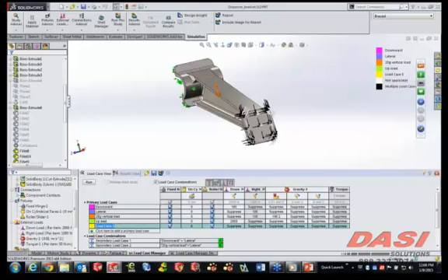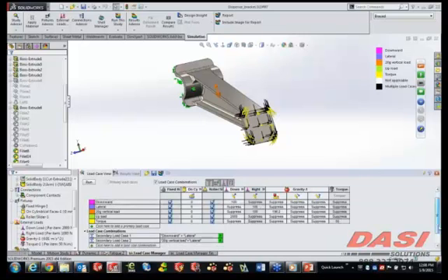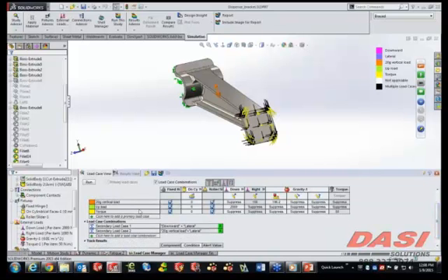We'll call it whatever we want. And now I can turn on whatever restraint or force I want, in this case the torque force. You can also create these load case combinations. Now, what a load case combination amounts to is different scenarios combined with each other in a different way.